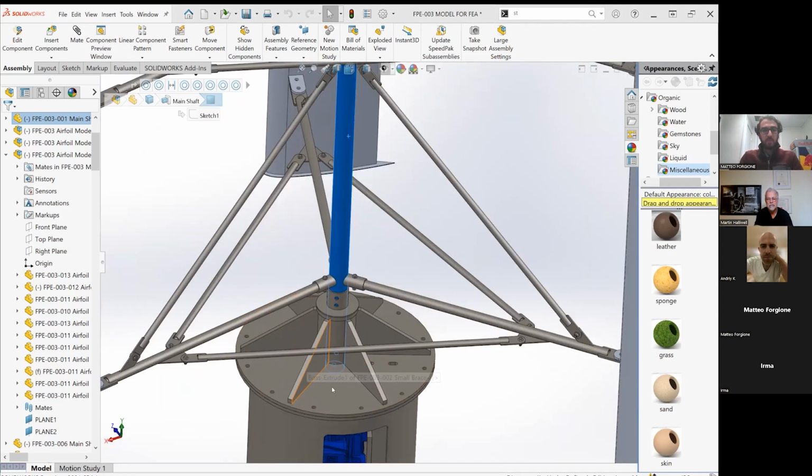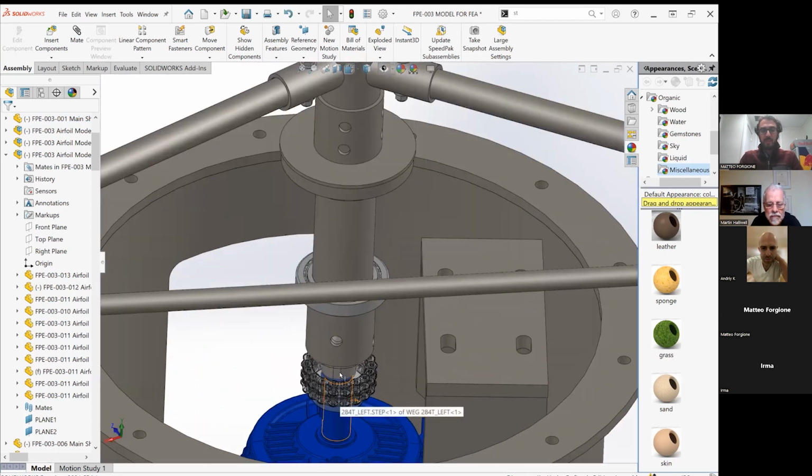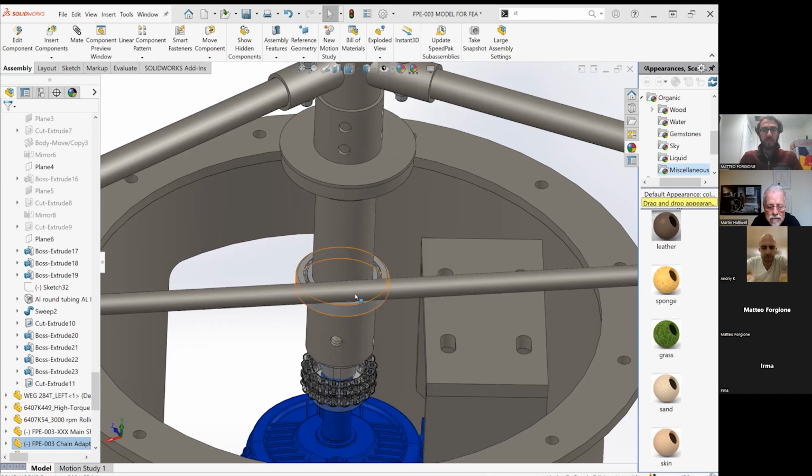So then underneath the base plate, we've got this heavy duty chain coupler. So you can see here, double chain. You have a sprocket connected to an adapter shaft, which is machined here. And that's machined out of solid 4140. And that's bolted 2 bolts directly through. For some reason, it's not letting me show that. I was going to isolate that, but I can hide stuff easier here.